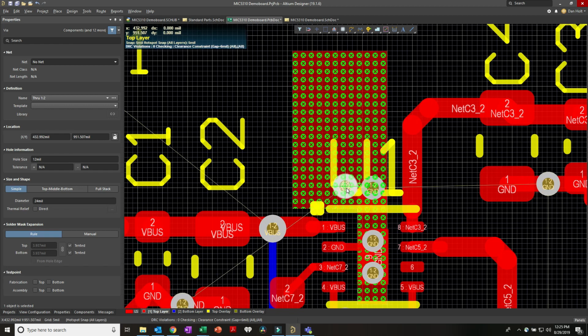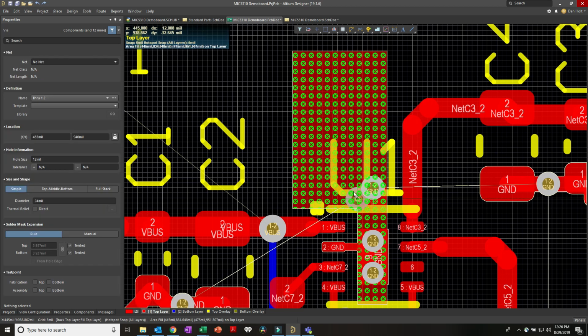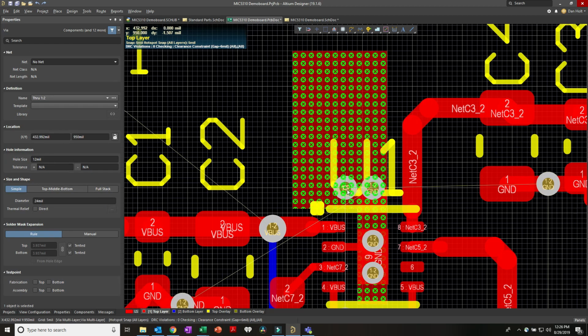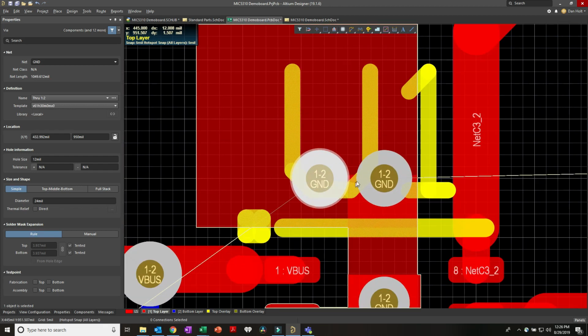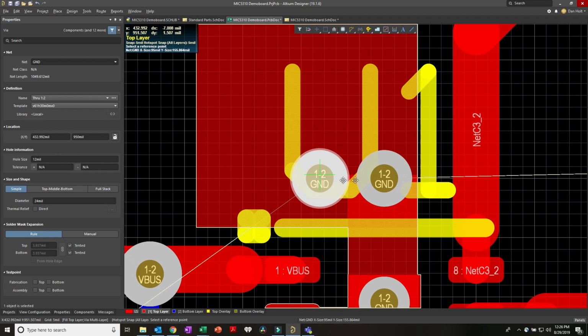Now this is an LDO, so I guess you could say it'd be nice to spread the heat around more. So I'm going to place a fill. So PF, I'm going to place a fill, and let's just kind of stretch it out kind of long here. And you can see where I'm going to run into violations. And perhaps there's better ways of doing a couple of these things. Maybe I'll just back off here. You can see how close I can get before I get a violation.